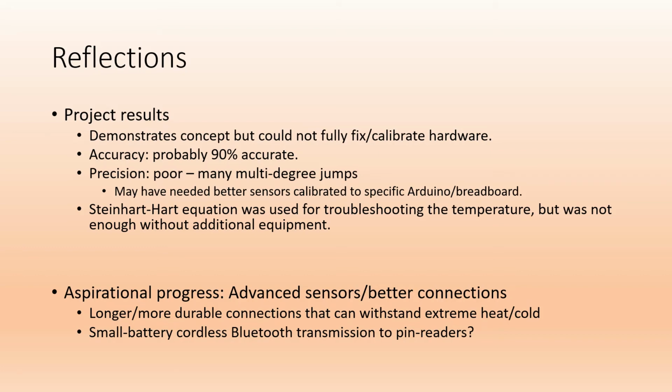I had tried, because I'd seen a lot about the Steinhart-Hart equation, to use that and to manipulate the readings and adjust for the voltages. But without additional voltage testing equipment to see whether the source was the Arduino or the thermistors themselves, the effort was fairly fruitless and futile, so I unfortunately was not able to progress further with that aspect.